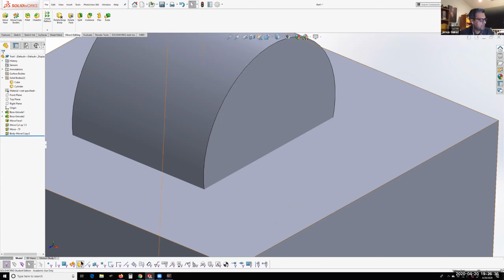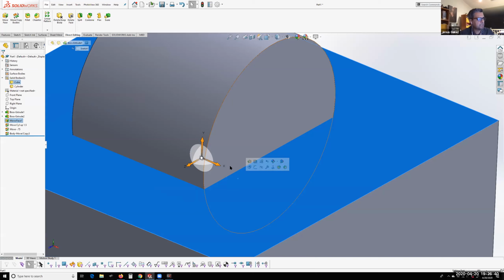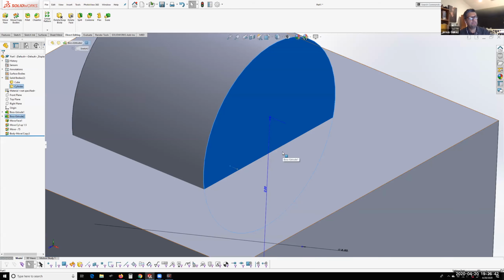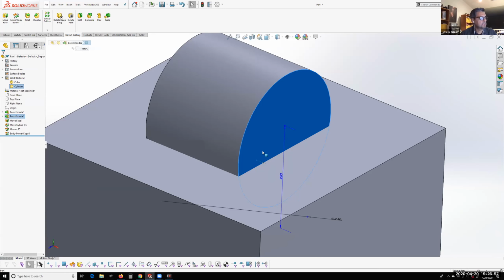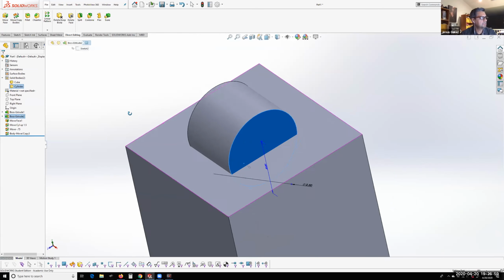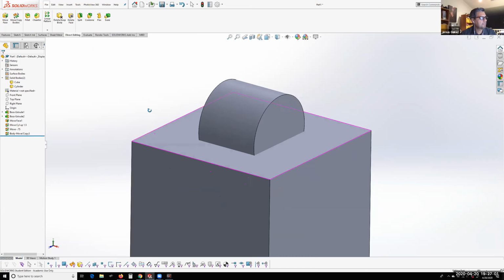And that's also why you wouldn't be able to fillet this face with this face, because there is no shared edge there. So this is a quick clue as to whether two faces share an edge. Since there's no black line there, no, they don't. That's just a quick tip to identify something like this.